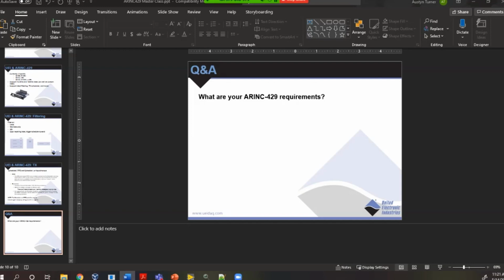Can I use this board in a cube? Yes. So all of our boards can be used in any form factor that we offer. So although in this demonstration there was a diagram or a picture of a DNR board or rectangle board, all of our boards work throughout any of the form factors. It's also worth noting, though, that you can't take a DNR board and plug it into a cube, which is a DNA board. There's a slight difference between the form factor of how they plug into the backplane, and that's the only difference between the hardware. So if you're developing software and you're writing it for a normal rectangle, and then later you want to go to a military chassis, the software will be identical. So that board can be used in all the various form factors.